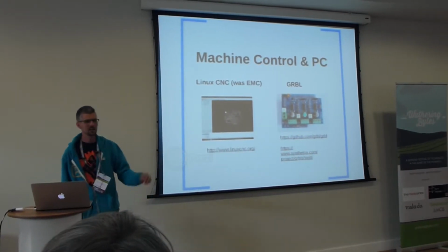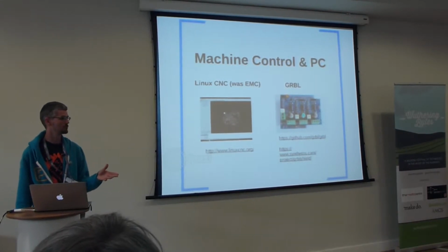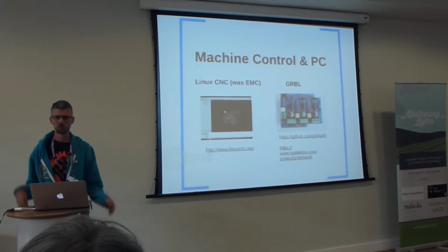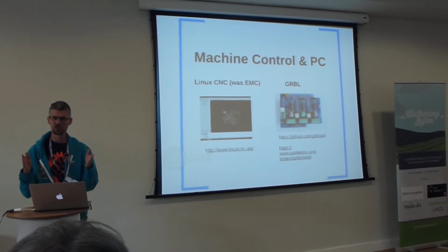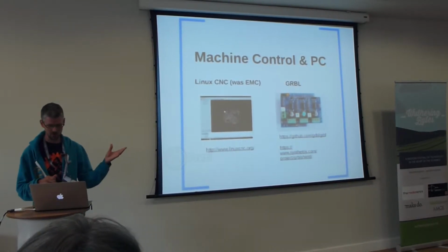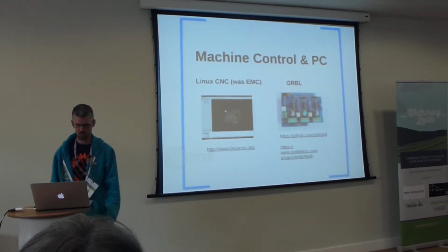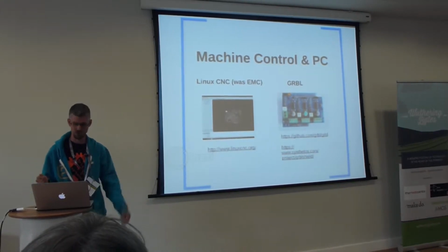It comes on a live disk, so it's been optimised for real-time usage. When you're generating the signals that drive the stepper motors, you want them to be really precise so you get smooth movement. It comes as a kind of CD that you can boot, and then you can install it if you want to make that change permanent. You can also just try it out.